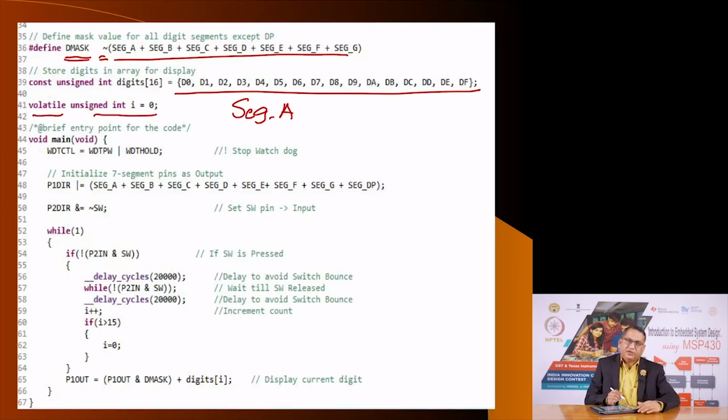We have covered interrupts, and we know that volatile is usually when you are interacting between a main program and an interrupt subroutine. In this case, there is no need to declare this variable as volatile. Also, it is not needed that this variable, because it is outside the main loop, appears to be declared as a global variable. There is no need for this variable to be a global variable, but it does not hurt. Now, let us go inside.